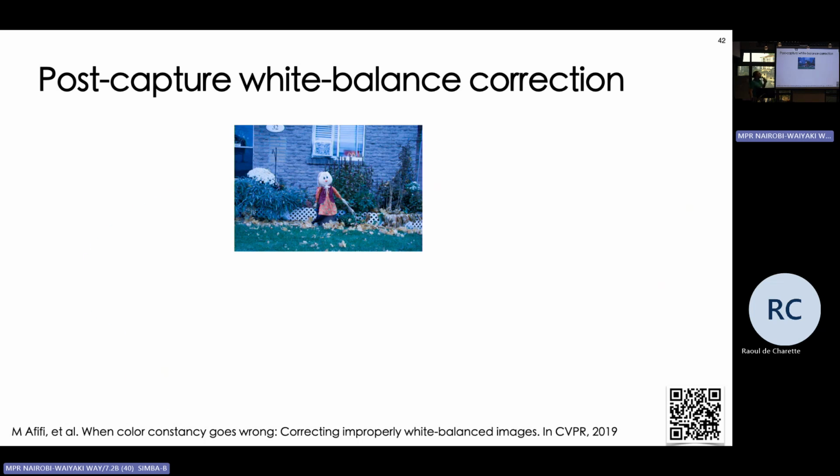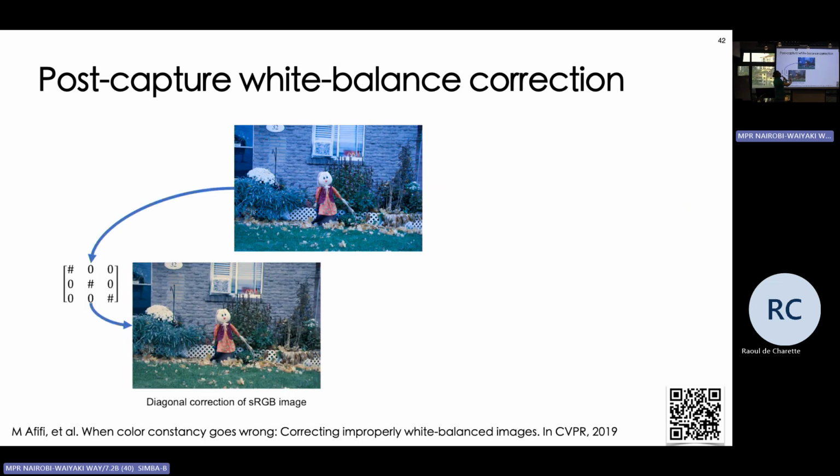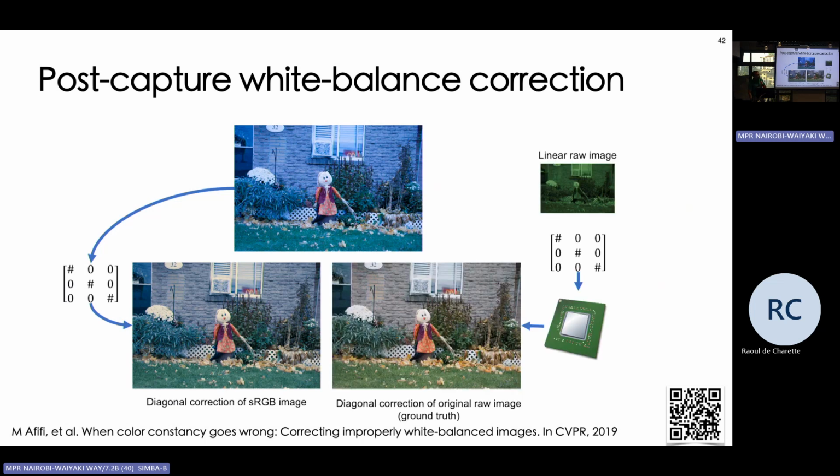So let's go with this. I will manually select a white reference point to represent what kind of bias in this image we try to remove. This is the best case because there is no estimation; I just manually select a good reference point. Let's do the diagonal correction, similar to what happens in the camera ISP. And it's good, but as I said, to appreciate how bad or good it is in colors, we need to see the best version and compare. So this is the best version.